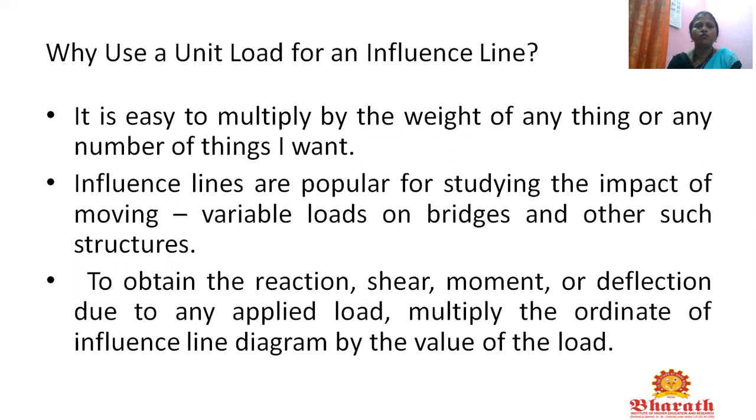Next, we are going to see why a unit load is used for the influence line. It makes it easy to multiply by the weight of anything or any number of things I want. Influence lines are very popular for studying the impact of moving, that is variable, loads on bridges and other structures.